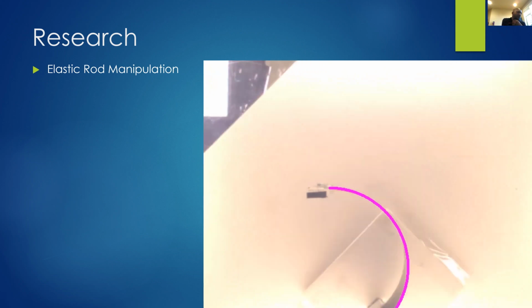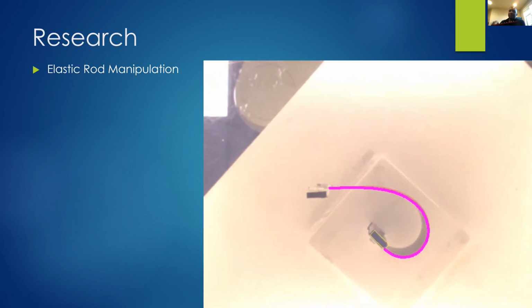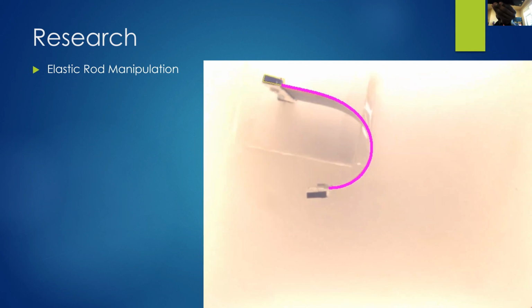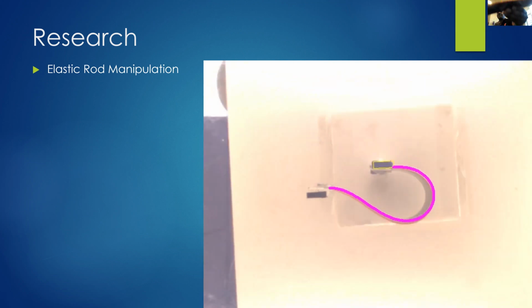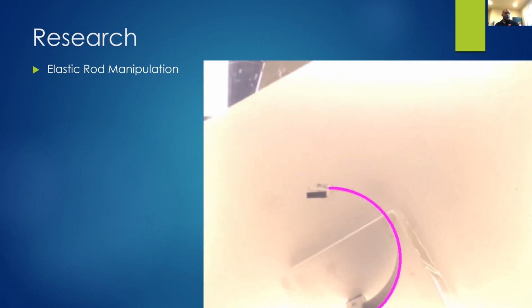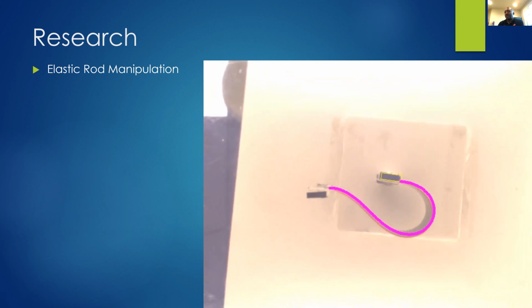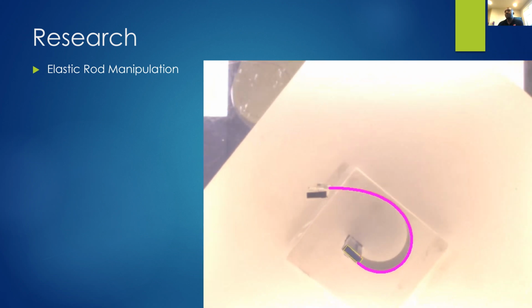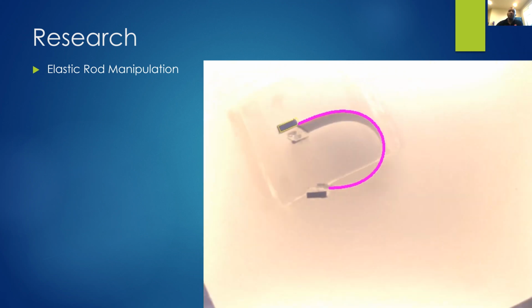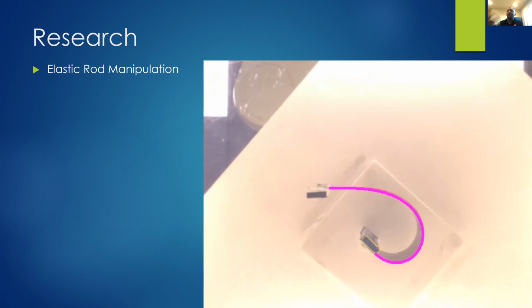And so the strip here is what we're using. And so we do have these markers. And so we're using the tracking of these markers to provide some level of feedback for what is the shape and doing these measurements. The computer vision is giving us a direct measurement of how the strip is moving. But it's sensor fusion, where you do have a force and you also have some type of visual feedback.